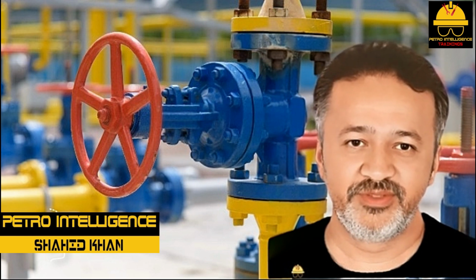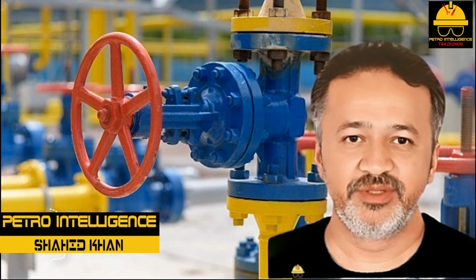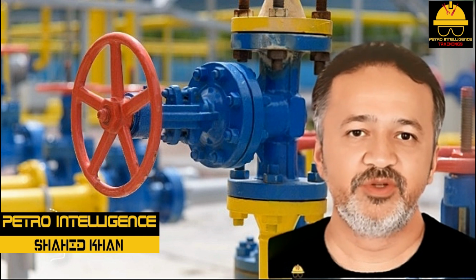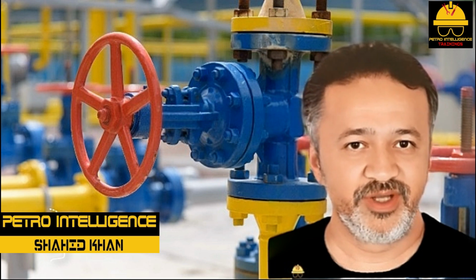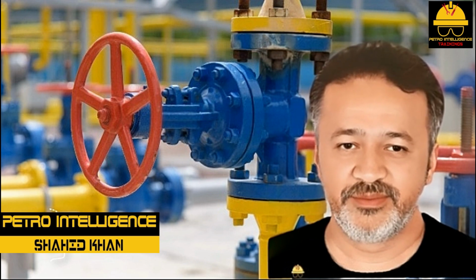Ball valves and plug valves have a hollow ball or plug-shaped movable element in the center of the valve that rotates into the open or closed position. These valves provide very little restriction to flow. They should not be used for throttling service or in high temperature or high pressure service. Check valves are used to control flow direction and to prevent contamination of or damage to equipment.